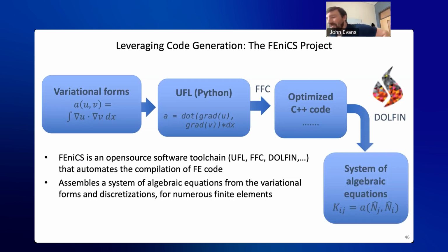I don't want to speak too much to the FEM crowd about using FEniCS, but my main inspiration for talking about it here today is that we should be able to leverage immersed analysis in FEM, interpolation-based analysis, almost as simply as it is done inside of FEniCS, which leverages UFL to do a human readable implementation of bilinear forms and the like.